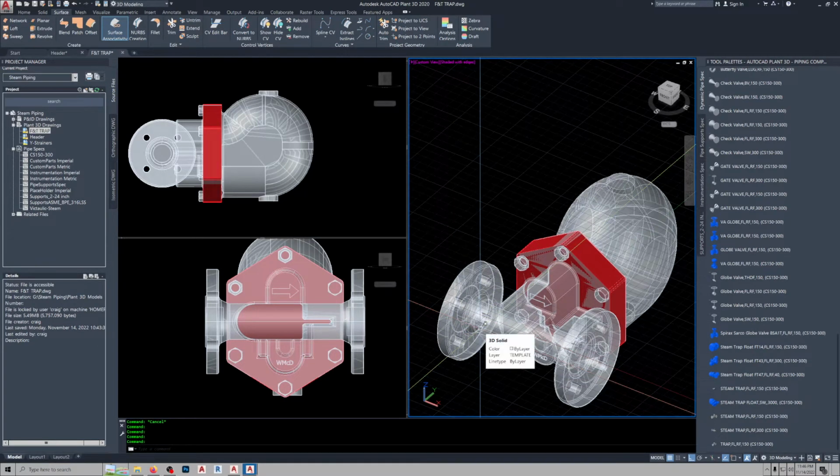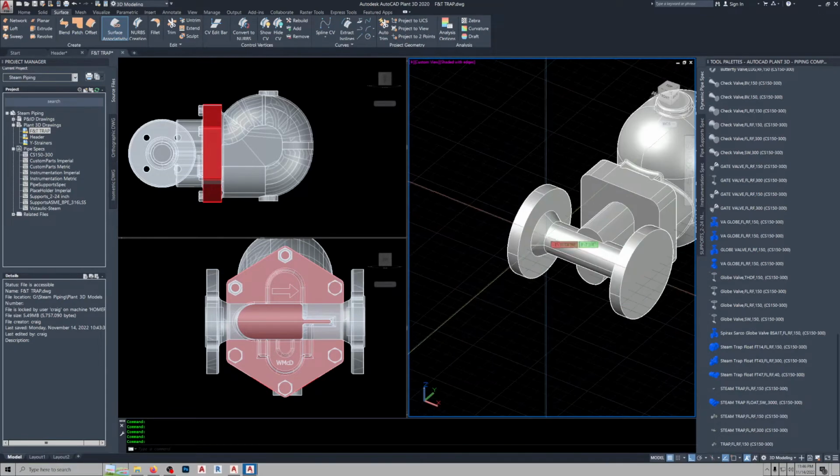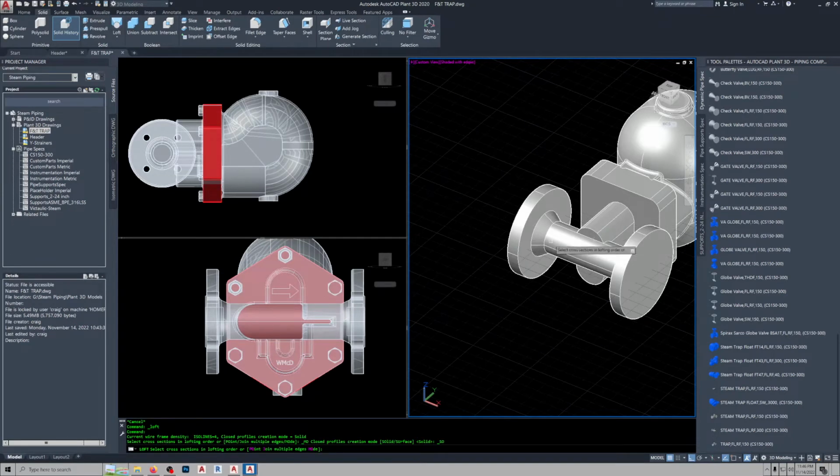It's mostly extrusions. The only thing you have to do a little different is use a loft to get this, and then from then on it's extrusion, and you only have to do one and mirror it. Now you'll have a line in here. You want to make sure you delete that line once you get done with modeling this portion of it.